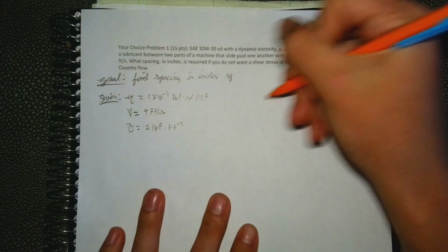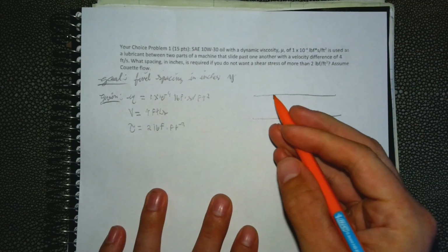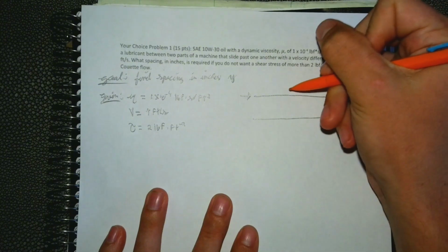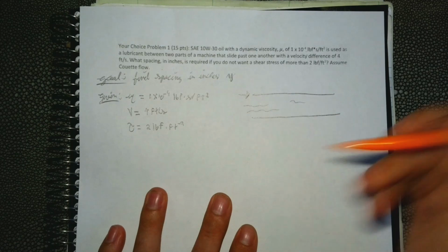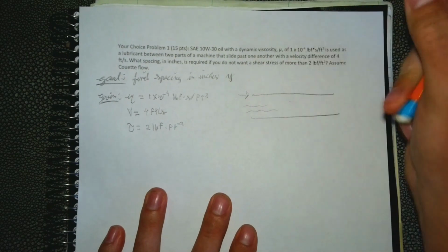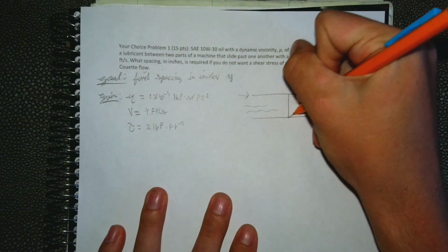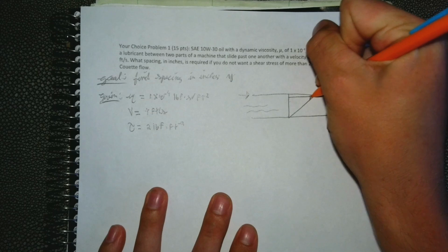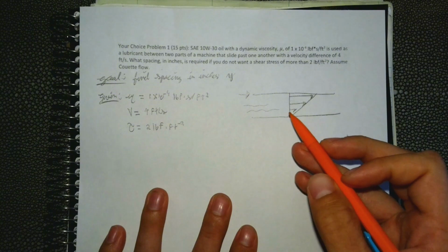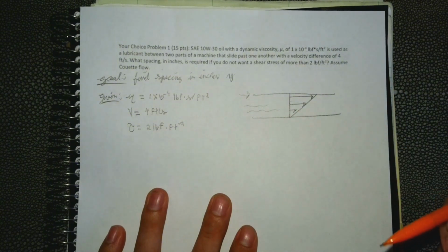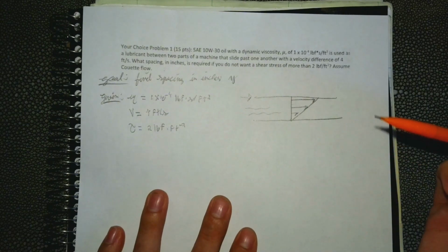All Couette flow is, is when you have one wall that's moving and one that's not. So let's say that this wall is moving, and then this wall moving causes a flow of water or some liquid. This wall is stationary, this one's moving. When this water is flowing, it will create a linear velocity gradient. It'll look like this. The velocity will be fastest at the top, but the biggest thing that you need to know in Couette flow is that the velocity gradient is linear.